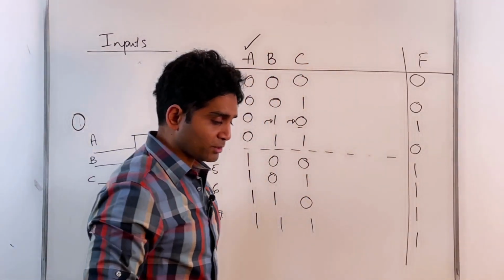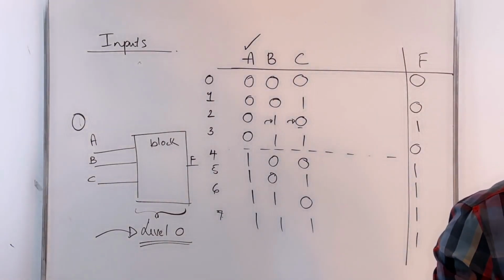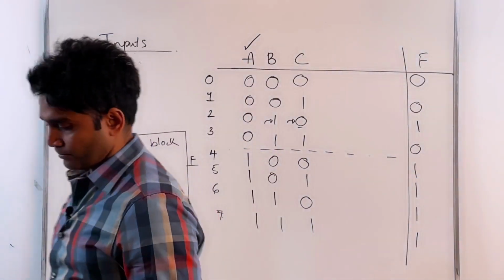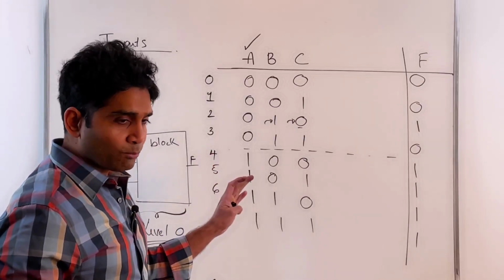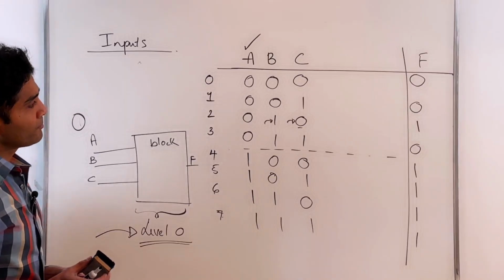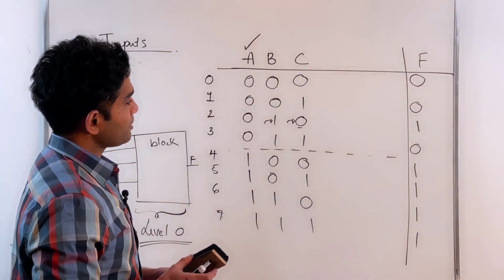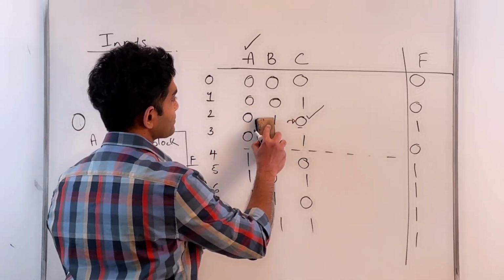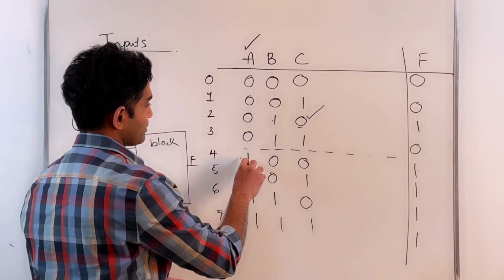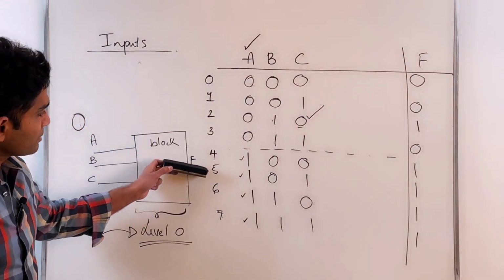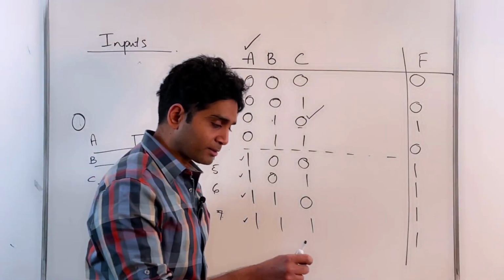So the truth table corresponding to the problem specification for the example that we just took corresponds to this. Now, moving forward, from this truth table I want to get a logical expression. How do I do this? F is true for this condition, if my input combination is this, or my input combinations are these. If those input combinations occur, F is true.